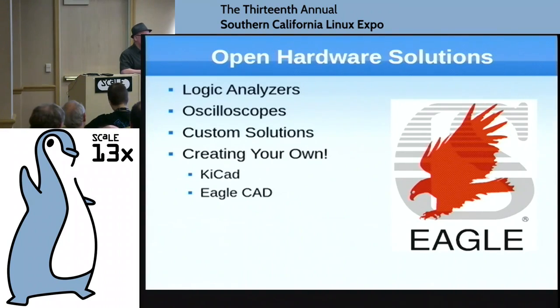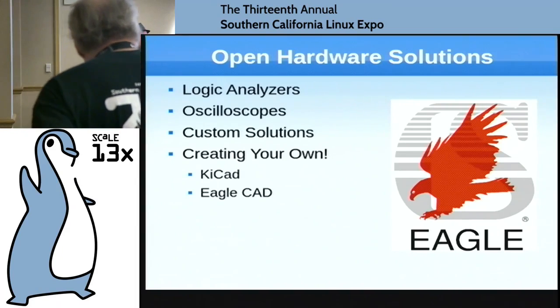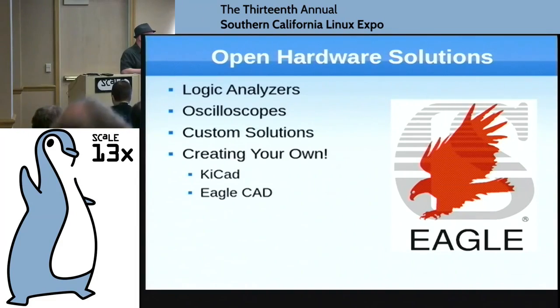In fact, companies like SparkFun often provide their libraries of what they've done, so you don't necessarily have to design your own parts. You can download one of their libraries and get things like LEDs, push buttons, switches, all the minor ICs like voltage regulators. These are already done for you in a library, and you can share these files with other people. So EagleCAD is still at this stage probably the design tool for the hobby community, but we hope to see KiCad replace that in the near future.